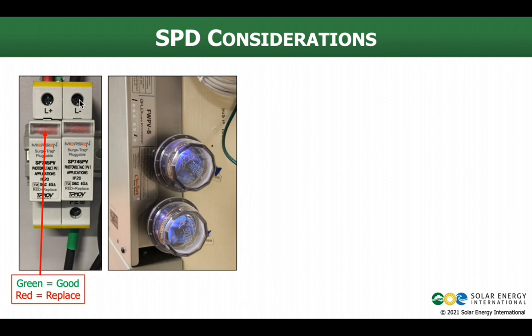Some of them aren't that way. You have to replace the whole body, which means disconnecting these conductors, which are energized, right? Here's a positive, here's a negative. They're connected to a bus bar and an inverter or a combiner box. They are connected through the high impedance surge protection device to ground. And if there is that transient over voltage, transient over current, then our circuit becomes much lower resistance and current can flow through there.